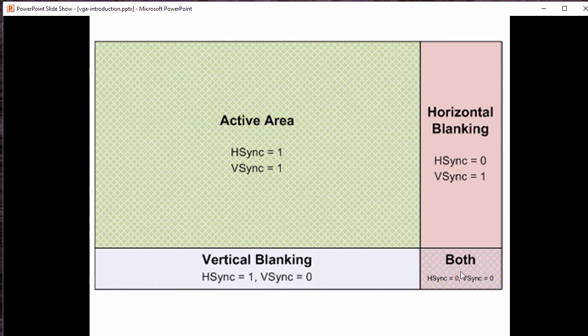So speaking of those concepts, the VGA monitor that you are looking at is this green part here. And that's called the active area of the screen. So if you're using a 640 by 480 image, this is 640 columns by 480 rows, 1920 by 1280, whatever your resolution is of your VGA monitor. This particular project is going to be focused on a 640 by 480 display. To the right here, you might not know about this, but it's here. This is called horizontal blanking. This is actually time when there's data being driven to the VGA monitor, but nothing is actually being displayed. Vertical blanking, same concept. This whole bottom box here is the vertical blanking box. This is when data is being driven to the monitor, but nothing's actively being displayed. So active area, inactive area right here.